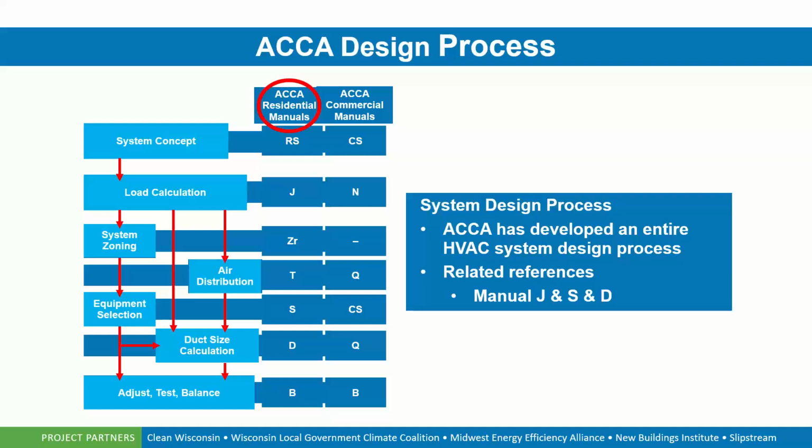trying to get our ACCA Manual J in place, or the load calculation. Again, that determines heat loss and heat gain based on code requirements in the building as designed. And we'll expand on that here in a few slides. So the next step in this, obviously, is a Manual J. We design the model within the software, knowing our building components, our doors and windows, our insulation values, orientation of the home, the size of the home, room by room calculations within the Manual J.